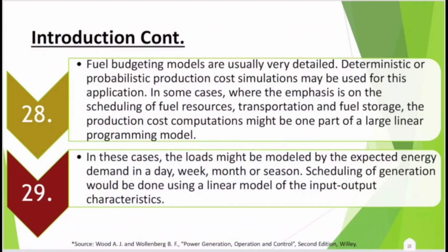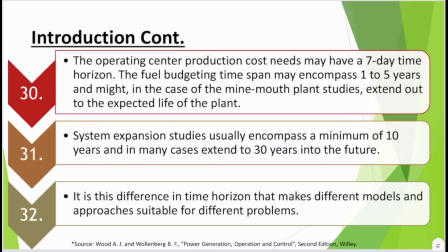Okay, so deterministic or probabilistic production cost simulations may be used for these applications. In some cases, where the emphasis is on the scheduling of fuel resources, transportation and fuel storage, the production cost computation might be one part of a larger linear programming model. In these cases, the load might be modeled by the expected energy demand in a week, because I'm getting into the probability. In a week, month, or a season, scheduling of generation would be done using a linear model of the input-output characteristics. The operating center production cost need may have a 7-day time horizon, weekly.